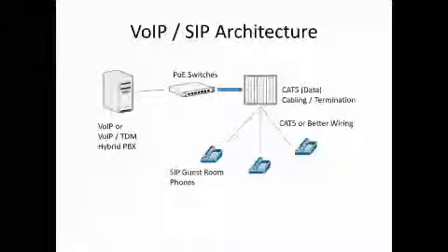Now here, the important thing to notice is that these PoE switches are inserted in between the PBX and the phones, and these can be distributed closer to the phones, but they do need to be PoE, or you have to plug each one of these phones not only into the cabling jack in the wall, but also to a power outlet nearby each phone. And that gets cumbersome. It's ugly. It is not something you want to present in a guest room. So PoE switches are required for this if you want to do it right, and we're going to do our cost analysis that way.